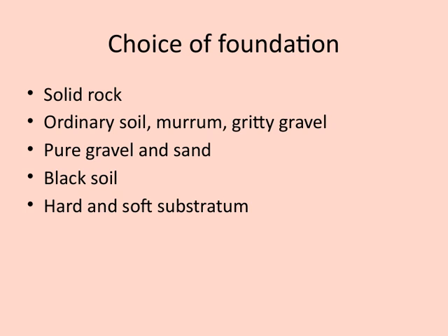Then there's pure gravel and sand, which are generally well-draining but can be less stable on their own, so they may need reinforcement or mixing with other materials. Black soil is another option, but it can be tricky because it tends to expand and contract with moisture changes, so it needs careful treatment.